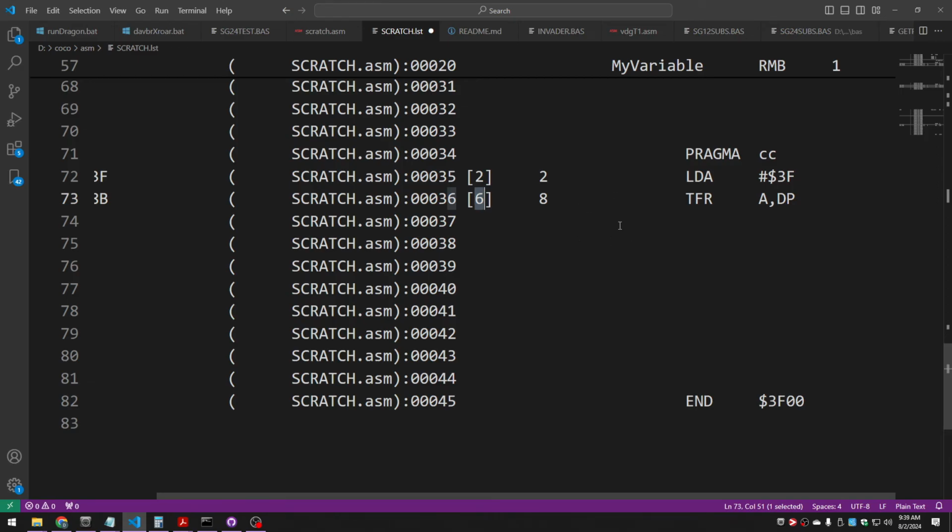This means that the number of memory accesses that you're converting from extended mode to direct has to be so many that they dwarf the number of times you need to change the value in the DP register. At a minimum, you want to be doing 8 memory addresses that you upgrade to direct mode for each time that you have to run this sequence of instructions.